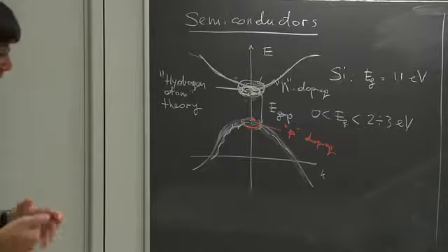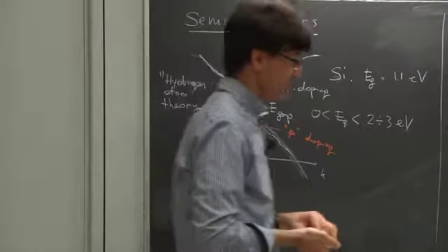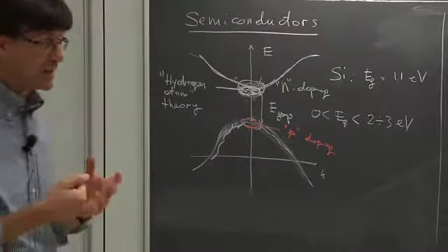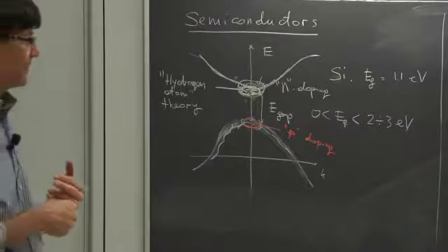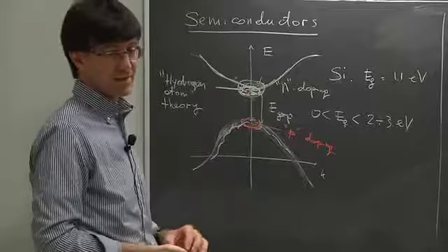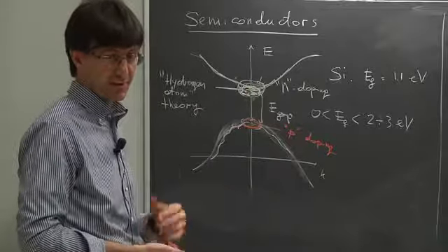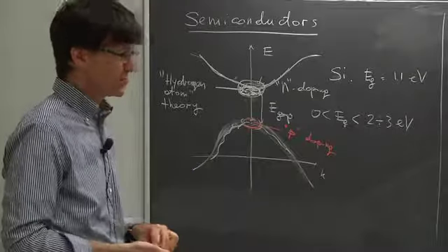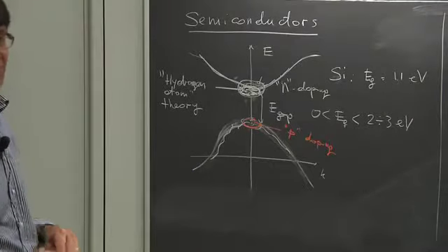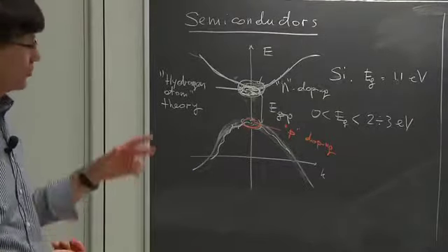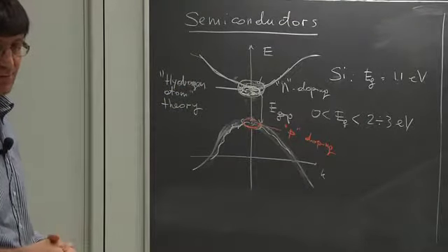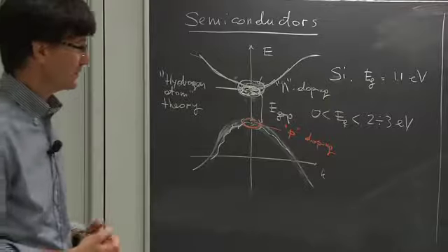So yes, you are introducing additional states, but it's rare. It's difficult to take advantage of these additional states. You are taking primarily advantage of the fact that these electrons are excited in the conduction band, that they therefore conduct. So there's not too much you can do with energy engineering. You do carrier concentration engineering here, but you don't really change too much the energy band by doing that.